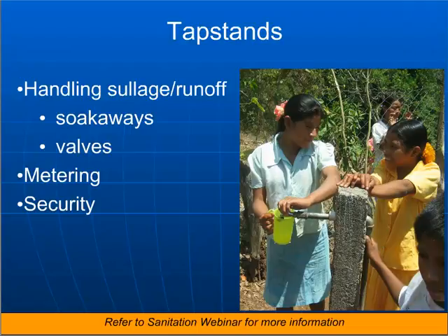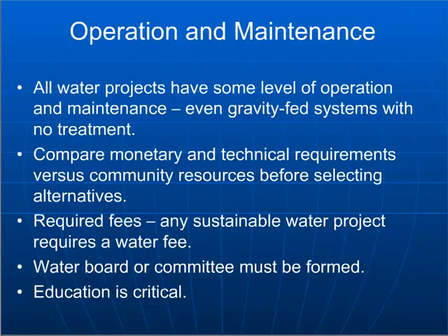So again, I think there's some more information on that in the sanitation webinar as well. The other issue to consider at the tap stand location is, are you going to try to include any type of metering device, and are the tap stands going to be secure? Are they going to be open for use 24 hours a day, or is the access going to be limited to specific times? Those are all things that need to be discussed with the community before you actually start building them, just making sure that everybody's on the same page.